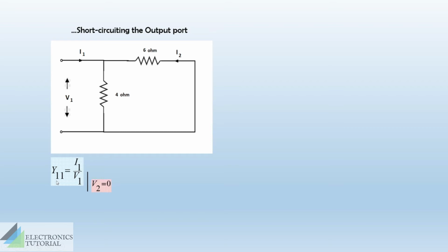We have to find the value of Y parameter from these unknown terms. So what we are going to do is make the numerator and the denominator of similar terms. For example, if I am able to represent this V1 value in terms of I1, then the equation will have similar terms both in the numerator and in the denominator. Then it will be easy for us to simplify the relation.